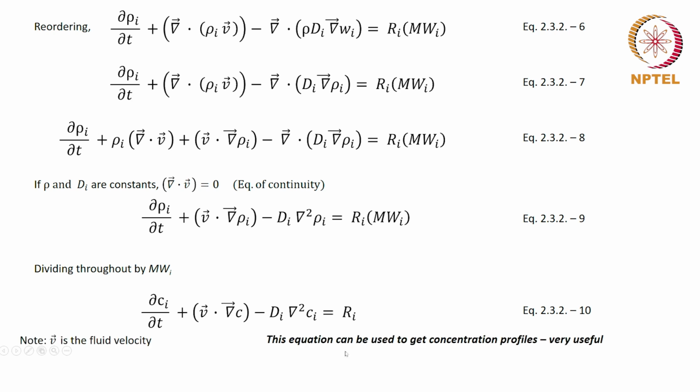This equation can be used to get concentration profiles, and that turns out to be very useful, as you will realize as we go through the various examples and you work out the various exercises. Okay. So, this equation is applicable if the density and the diffusivity are constants. The other equation is applicable in general. Okay. So, remember this. Here, of course, v is the fluid velocity.